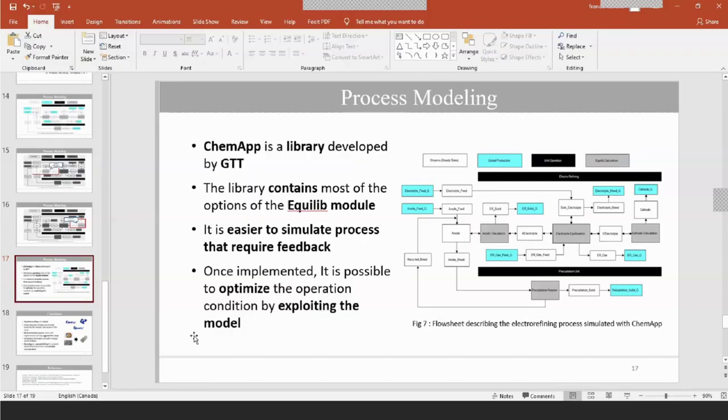We are talking about it for different reasons right now at the CRCT, but definitely that would be a better feature in FactSage, because sometimes you want to do a calculation and you're not too sure if, in this range of composition, the calculations are good or not. And this goes back to the quality of the database. If we add a lot of excess parameters and we don't care too much about the models that we're using, then we might end up with weird predictions, interpolation or extrapolation as a function of temperature or composition.